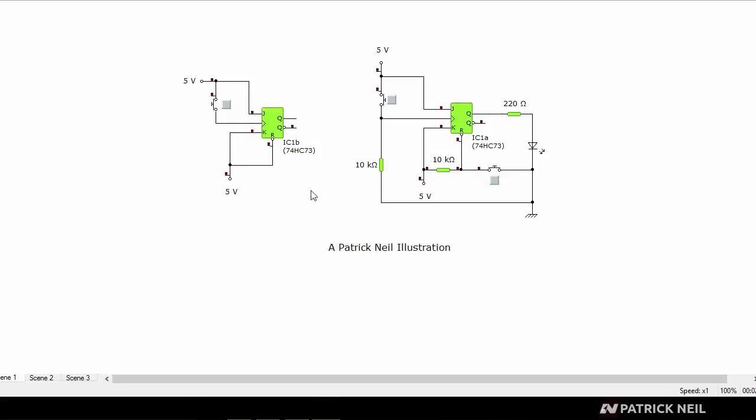Now, a flip-flop, as mentioned earlier, is a circuit that whenever it receives a sequence of voltage on the input, either from low to high or high to low, it will change the output to a state, and it latches that output in that state. Until you make that same signal again, then the output will switch back to the previous state. It's better for me to experiment to reinforce what I just said. For example, this circuit right now, this pin is low. Whenever I push this button, it will go high. Just like that.